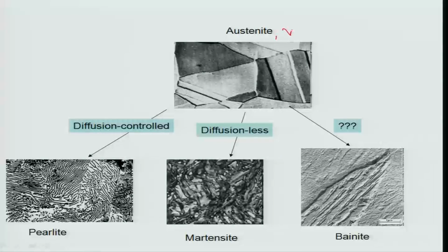So, our base microstructure is austenite, which is the gamma phase. We call it austenite, basically coming from the name of a scientist. You can see here these are the austenite grains, single phase, and if you cool it very slowly below the eutectoid transformation temperature, you can form pearlite. Pearlite has a lamellar morphology consisting of alpha solid solution and Fe3C. The white color thing is alpha, the black color thing is Fe3C. This will happen if you cool it very slowly or cool it normally.